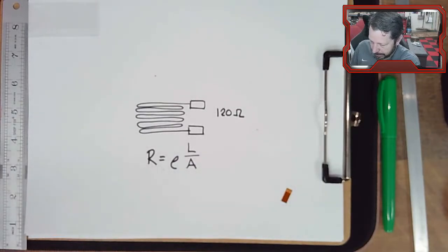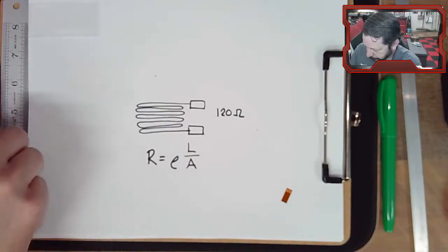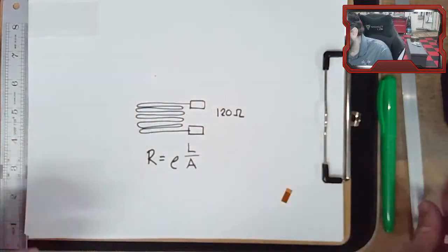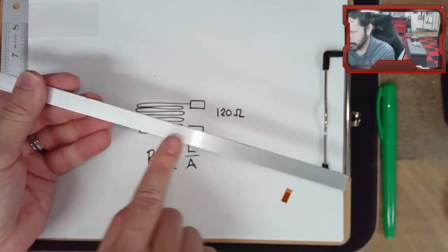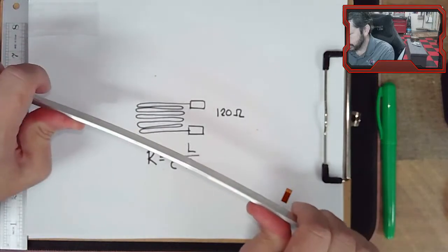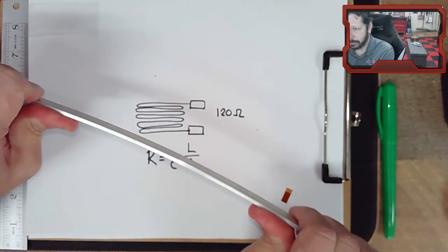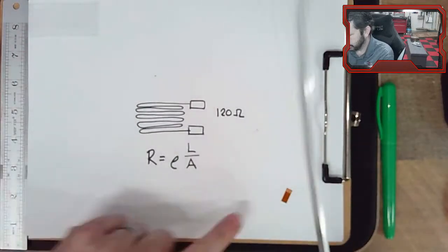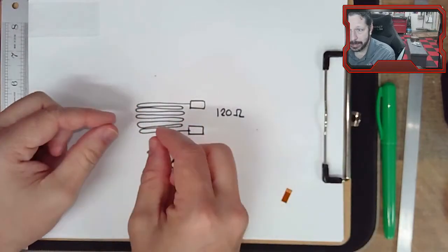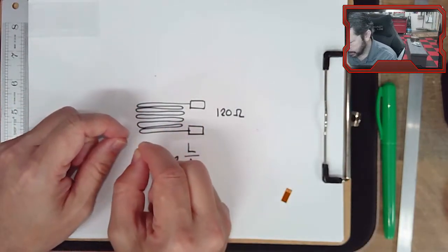So what you have to imagine now is as you strain, this is going to be mounted maybe on top of this beam, and as I strain it, putting tension on top, this thing is bonded to it, super glued to it, and it's going to get longer also.